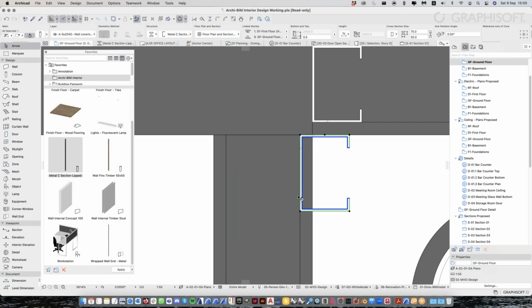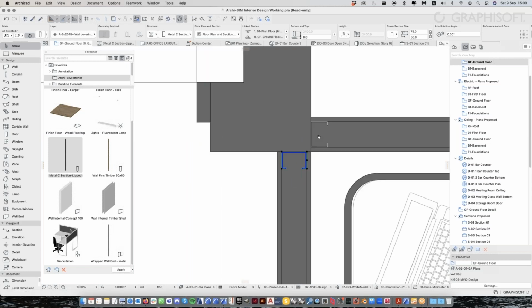And to rotate is Control E or Command E. So let me do E. Okay, you see this compass. I click on the rotation center and provide a reference line start point. If you check the bottom left, you see it will give you hints on what to do next. So enter the rotation arc start point. Start point is here, and I just want to rotate it 90 degrees towards this way. Okay, so I can just rotate. So this is how I would place this stud.